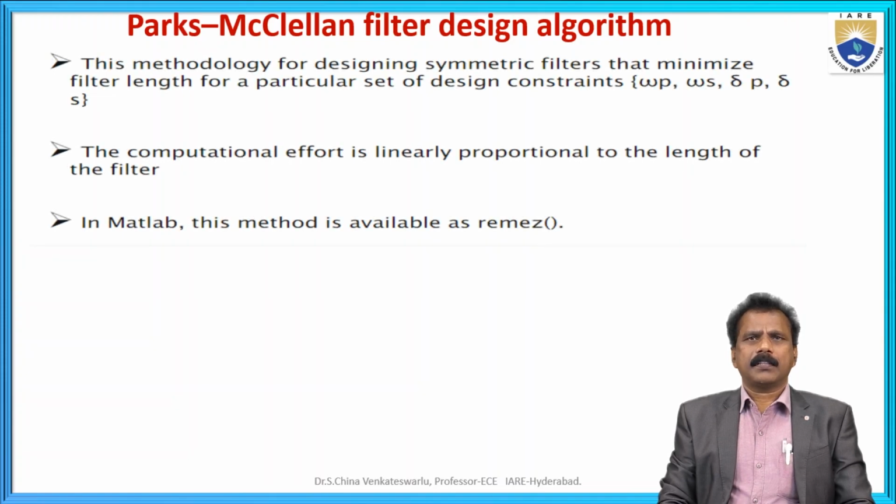Now we have to look at this methodology for designing a symmetric filter that minimizes the filter length for a particular set of design constraints, where omega p and omega s are the pass band and stop band edges, and delta p, delta s are the ripples. The computational effort is linearly proportional to the length of the filter. The other thing is that in MATLAB, this method is available as the remez function.